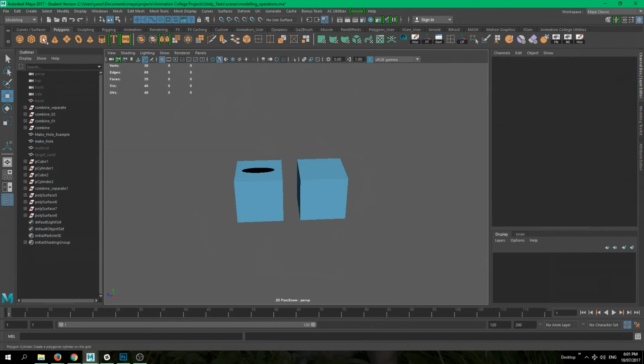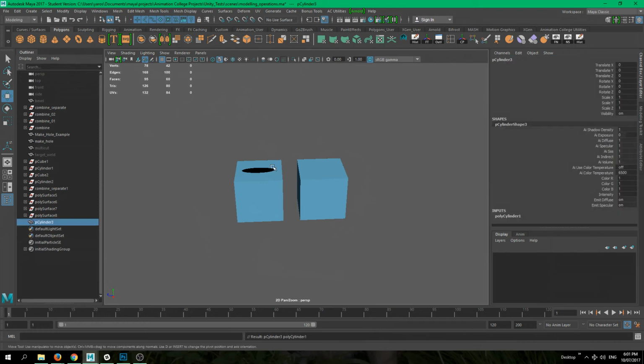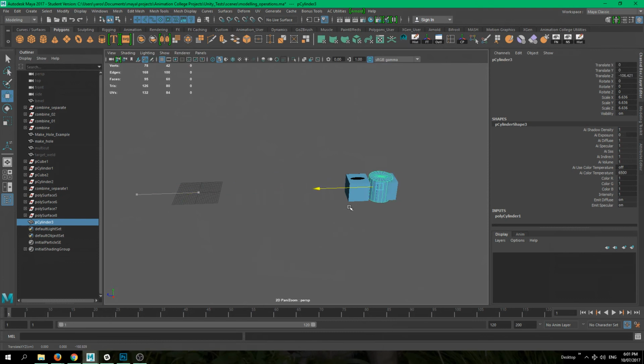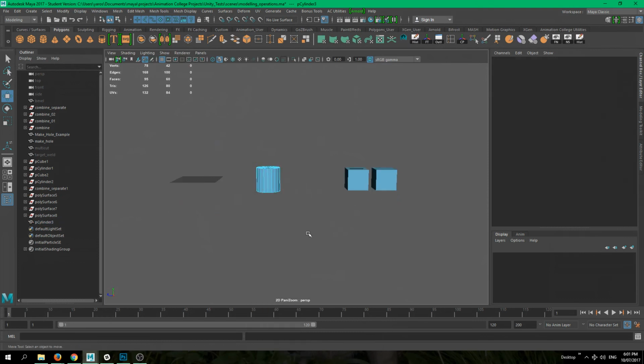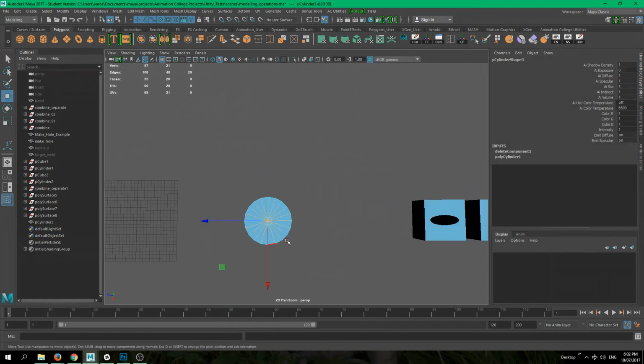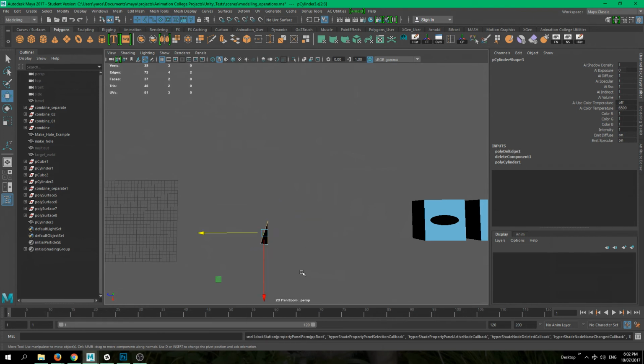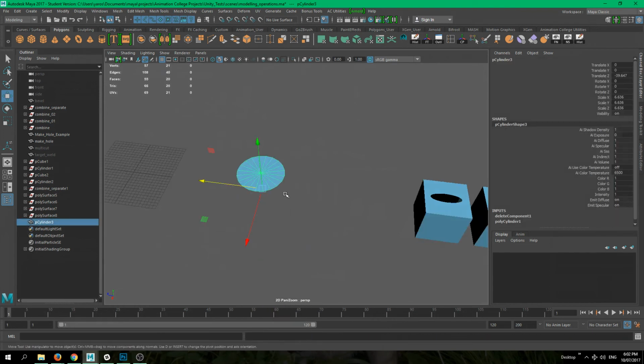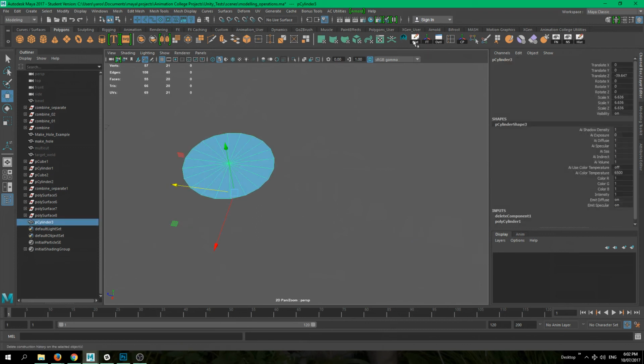So let's just try it out. Let's say we go and create something like, again, a cylinder. We're using them quite a lot today. Just scale it up a little bit. And what I want to do, I will get rid of all of the faces at the bottom. And I will also get rid of all of the edges, so that this is just one face. So shift right click, delete edge, and it breaks, which is fine. So we'll see if we can actually fix it.